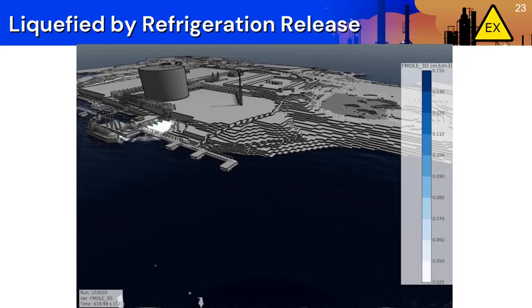Given that an LNG leak will expand to 500 times its liquid volume, a significant amount of flammable gas will be created from a small liquid release. The classification design must account for the various forms of release in an LNG facility. This may require that several models are used to predict release behavior. The assessment may require both a gas release and evaporative pool release to be modeled. In some applications, a CFD simulation may be needed to estimate the hazardous extents.